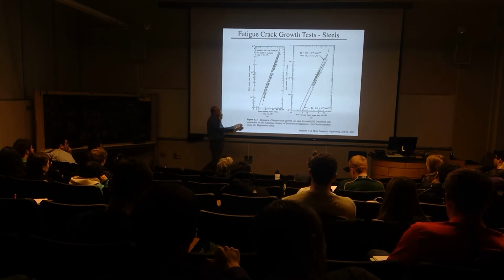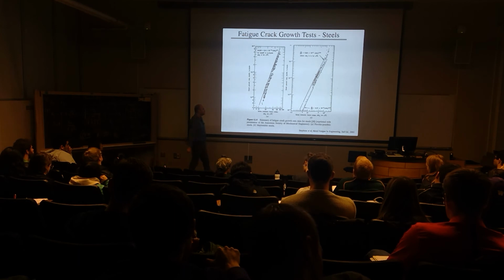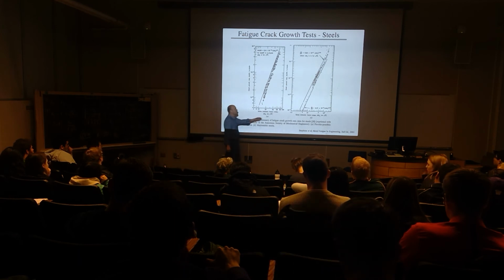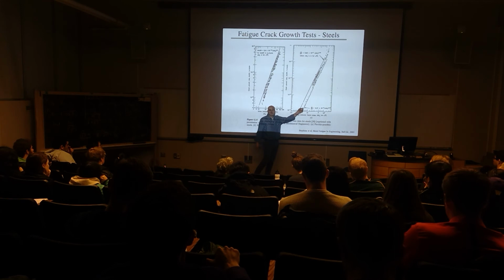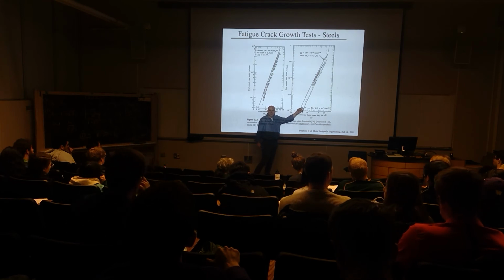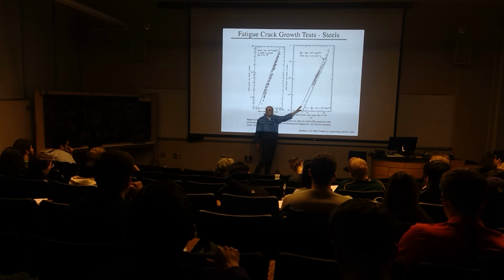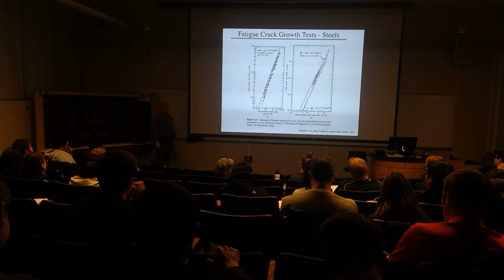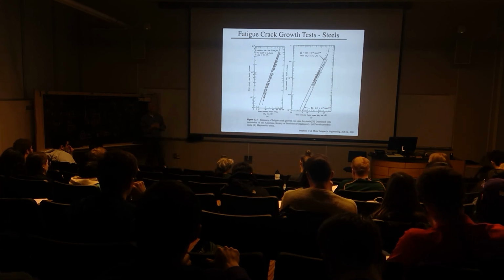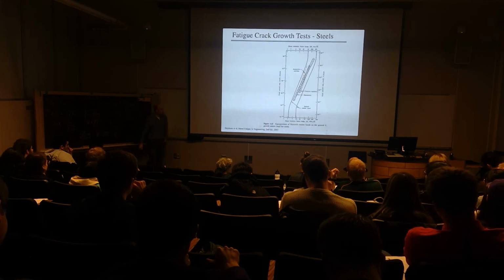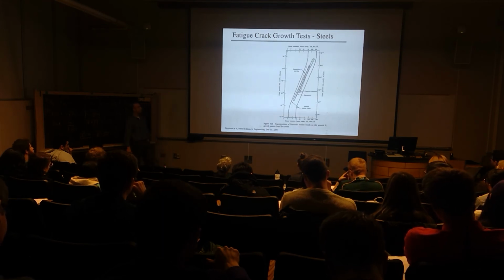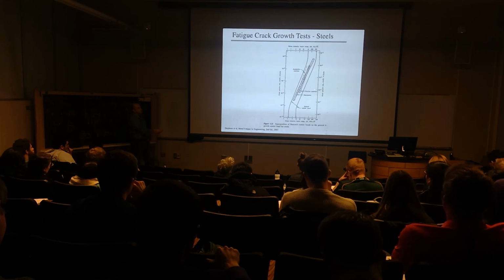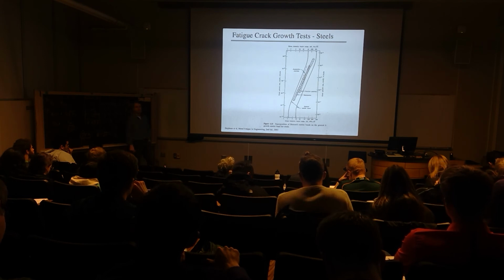Same kind of thing, the bounds now defining responses for the martensitic steels. This doesn't mean martensite, this means the martensitic versions of steels, for example, the stainless steels that are common in this martensitic condition, 400 series, etc. Tough materials, but they still undergo fatigue crack growth and follow the Paris law responses. Okay? We would use those for design or for checking something that will become evident in the fit. Here's a comparison of all the steels together, just showing you the bounds between the austenitic, the ferritic, and the martensitic steels, and the range of the bands that accommodate all those materials.